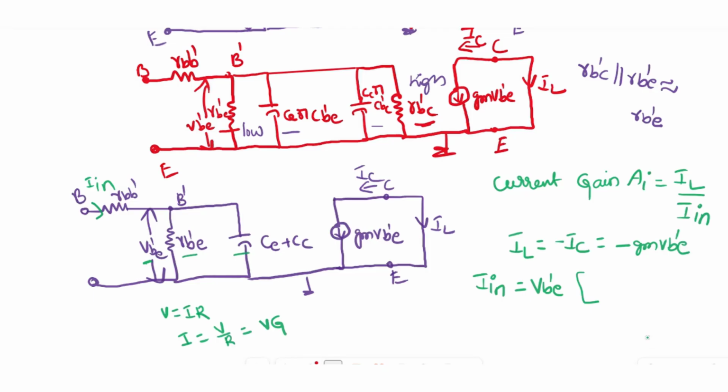So what is the conductance as the two are in parallel? Actually, for resistance in parallel you have to go for R1R2 by R1 plus R2. But we are taking the conductance. Conductance means you can just sum, though it is a parallel combination. That is the advantage of taking conductances. So the first conductance, 1 by Rb'e, you can write as Gb'e.